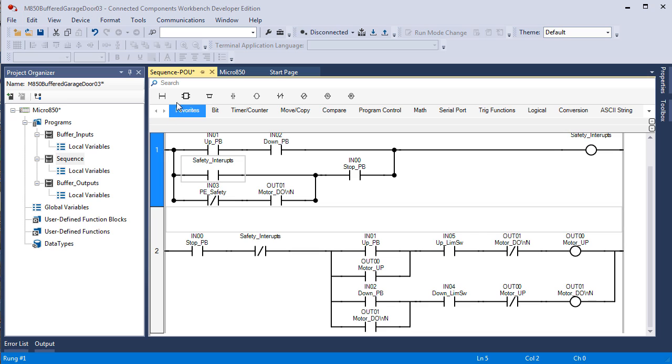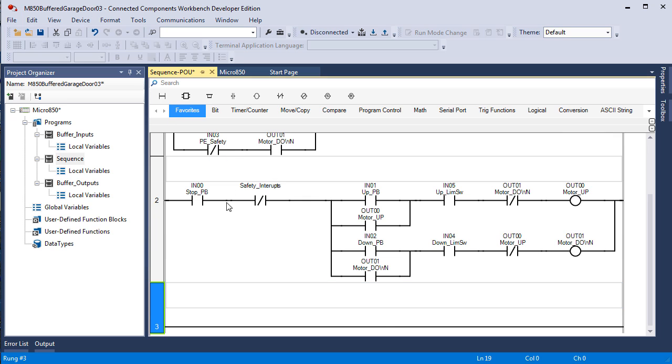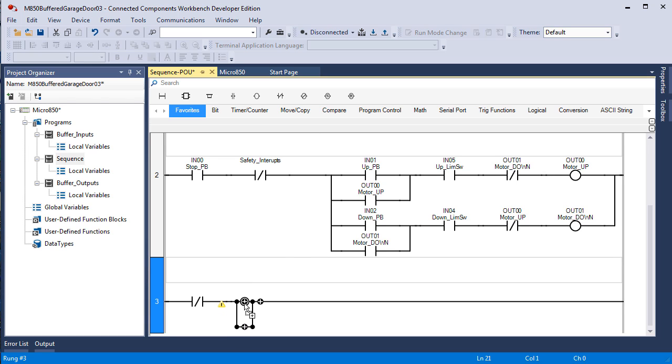So I'm going to drag a rung down and add a true if off. I single click on it and I have it. Just for grins, I'm going to single click on that and move this over inside. Now there's another way that we could have done it, so I'm going to back up and drag it down, and if I drop it here, it's going to look the same as it did by clicking on it. If I bring it down and drop it here, it goes around the true if off. Putting it after the true if off and then dragging the true if off inside, or just dropping it where it encompasses the true if off, you're still going to end up with the same results. But it's just nice to know you've got an option.